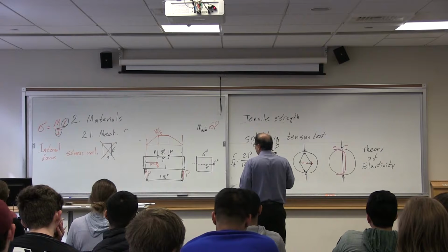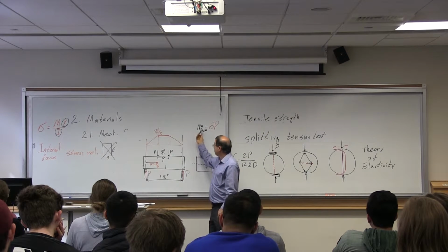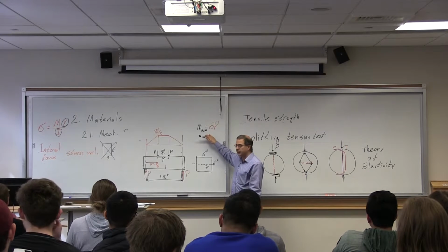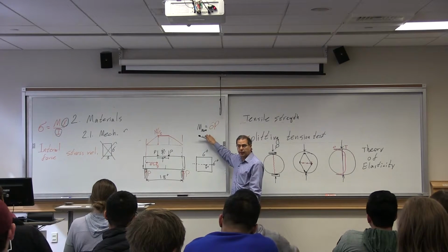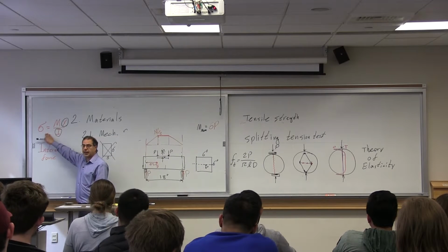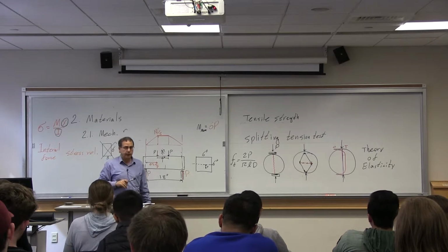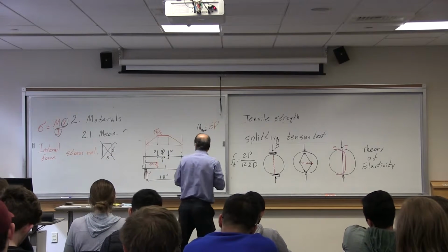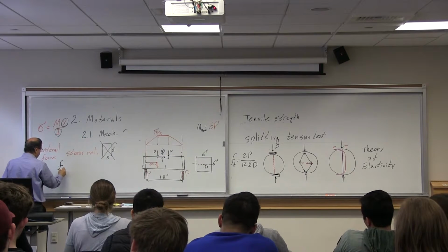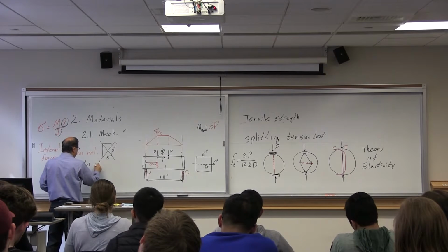So, what do we do? We find the force, we find the maximum moment, and we say, okay, that was as much as statics was helping me. And then we say, okay, what can solid mechanics do? Solid mechanics gives you this. You relate them, and you find your stress. That stress is called modulus of rupture.